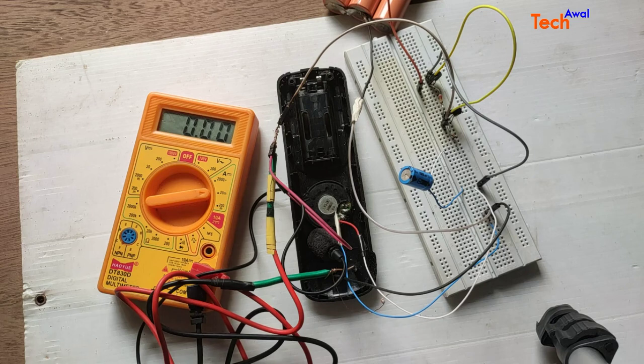Okay, so the region we saw now is the active region of the transistor, but since the capacitor is discharging, at one moment it will cut off. So now it is cut off, and the capacitor is charging. So this is IE, and IE reaches 2.22 milliampere. This is what we have seen. It takes around 30 seconds to charge and 4 seconds to discharge. So it is charging, discharging. The transistor is becoming active and passive, cut off during this phase.